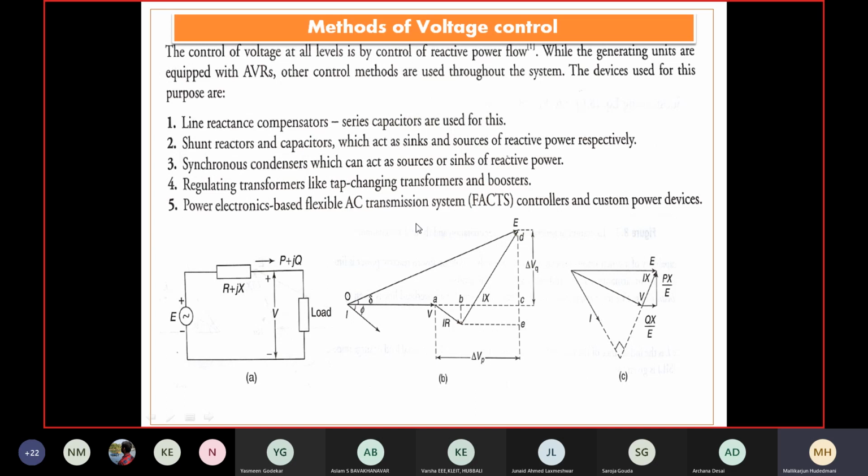So this vector diagram becomes basic for us. Later we can draw the conclusion that the projection of this particular side IX, horizontal and vertical, and the IR side's projection on the horizontal axis becomes AB.